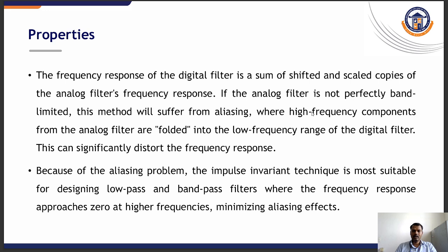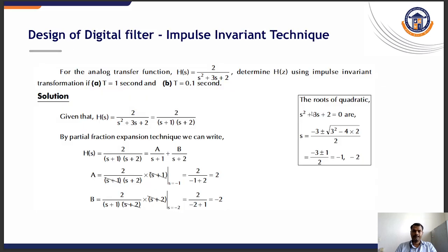And then, as I told already, it has an aliasing problem. Because of that, we cannot design low pass, high pass, and band stop filters. An example for designing of a digital filter using the impulse invariant technique.